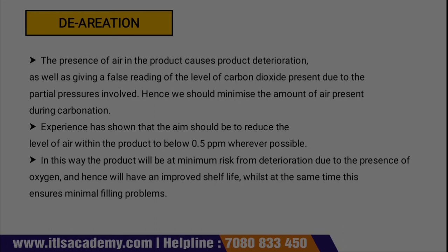So, what is deaeration? So deaeration, if for example there is any product, and if air is present in that product, then obviously air will deteriorate your product. Same with the beverage industries also. If in any product or any beverage there is air, it will cause deterioration of that particular product. As well as it starts giving a false reading of CO2, of how much amount of CO2 is present. Why does it do this? Due to the partial pressure that is involved.